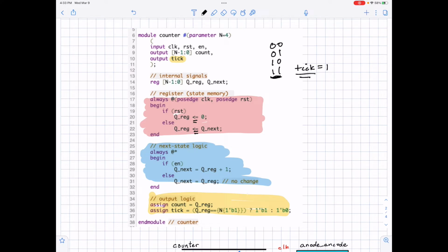All right, so if you had a 20-bit counter, it's going through and it's counting. It goes all the way up to 2 to the n minus 1, and then it gets to the end and it puts an output out. Okay, so you can see where you can slow down the clock by just having a bigger and bigger counter.